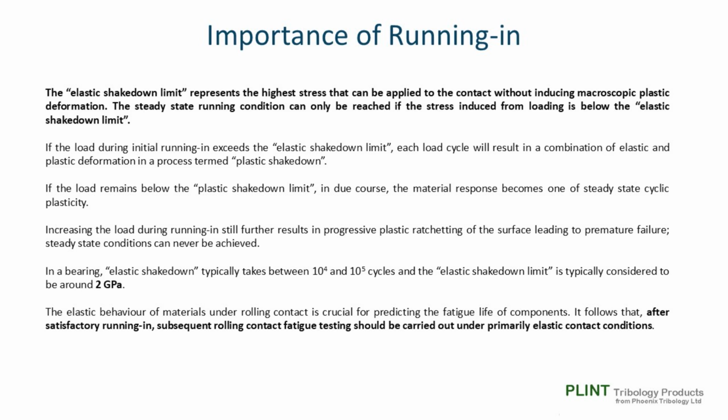The elastic shakedown limit represents the highest stress that can be applied to the contact without inducing macroscopic plastic deformation. The steady-state running condition can only be achieved if the stress induced from loading is below the elastic shakedown limit.